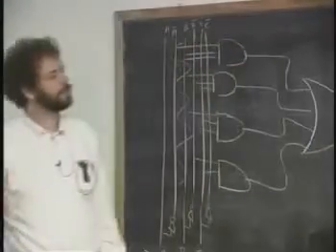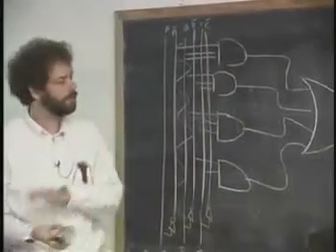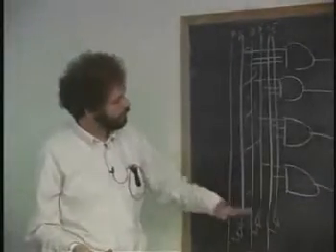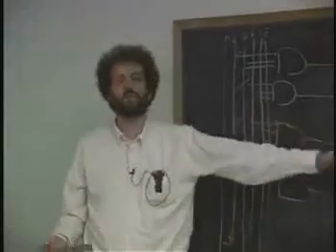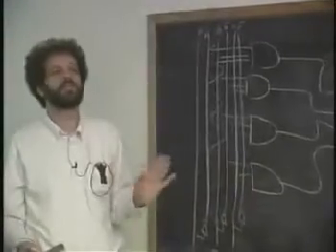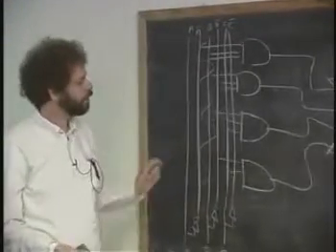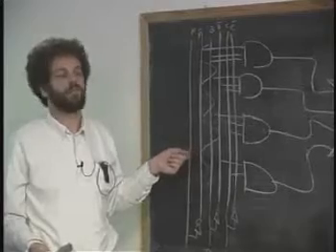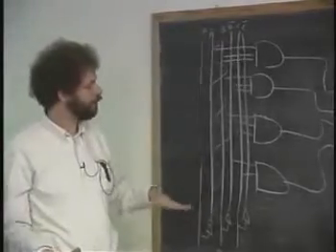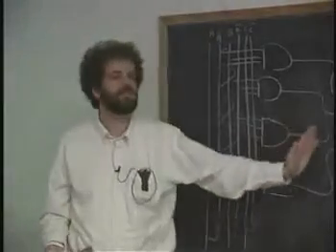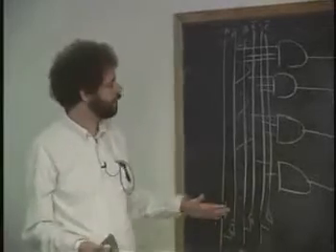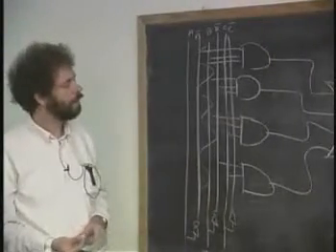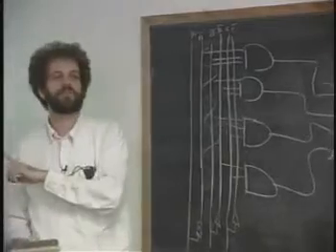And what we've just learned, first of all, and which I think you learned in the logic course that you took, is that this structure of the inverse, the AND, and the OR can do any function on Earth. Okay? But the question is, is this the most efficient way to do the function? Well, it seems to be the fastest, because after all, it's only 3 levels of logic, right? And how can you beat something that takes 3 stages of logic, no matter how complex it is? Well, except for the parity function.